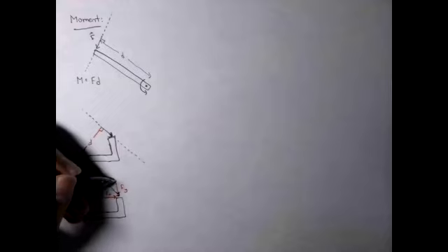But what was the point, right? The point of finding these x and y components is that now I can find my moment about my point O by looking at the individual moments that each of these components causes about this point. In other words, my line of action for my y force is this vertical line. And therefore, the distance between this point and my line of action is simply this horizontal distance, which I'm just going to call A.